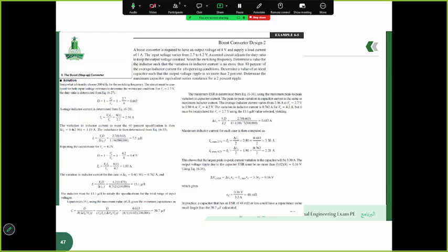The variation in the inductor current and the minimum required inductor size for continuous operation are then calculated for both input voltage cases. The design must satisfy the requirements for the entire input voltage range, so the larger of the two inductor values is selected. The slide shows that an inductor of 13.1 microhenry is sufficient to meet the specifications.